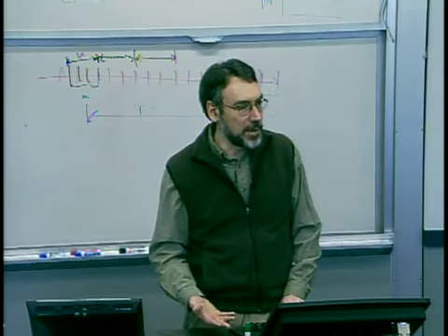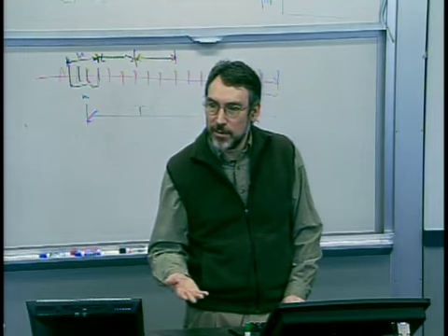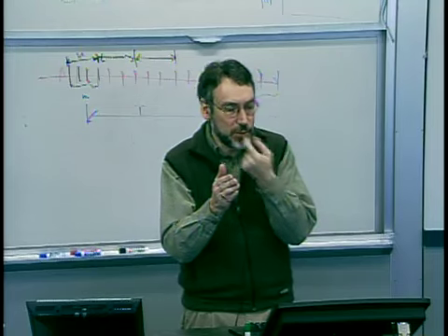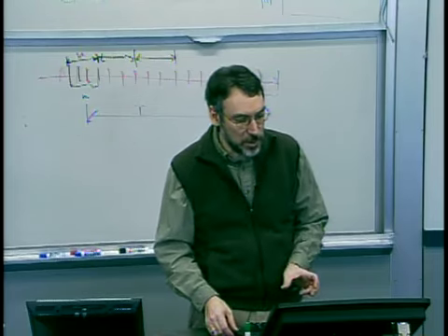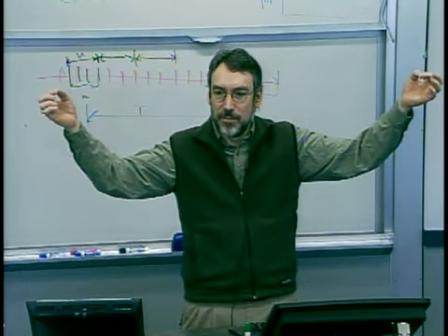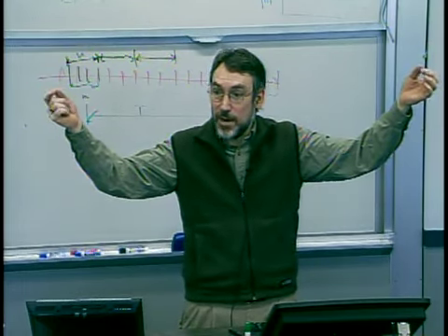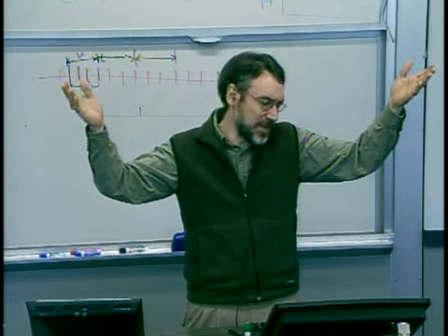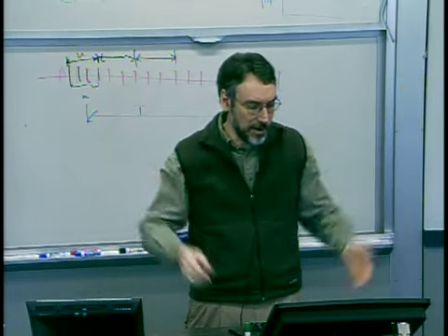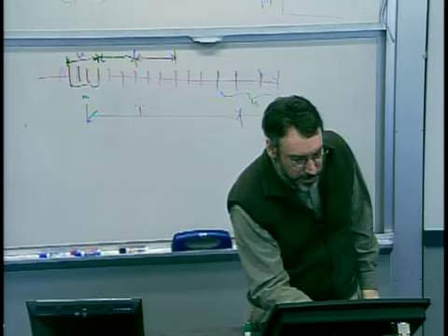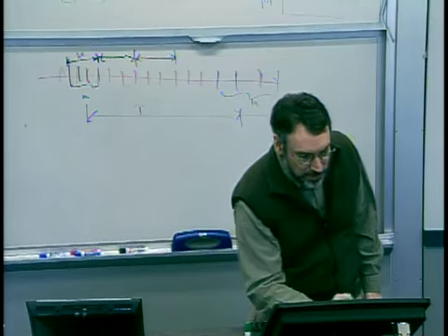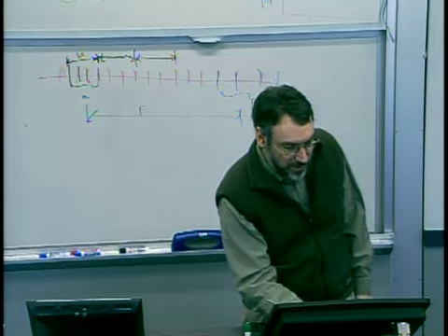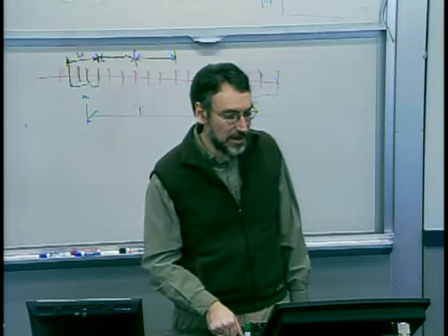Here's another situation. What's changed here? Now, in this case, my spread is much smaller. I've got a tighter distribution. And in fact, my upper spec limit to lower spec limit is basically 12 sigma. That's great, right? So that's a CP of 2. Now, I'm still off-centered. I'm mistargeted. And so in this case, my minimum distance from mean to the lower spec limit, that is the smallest distance, is still 3 sigma. So when I divide that distance there, I get the CPK of 1.